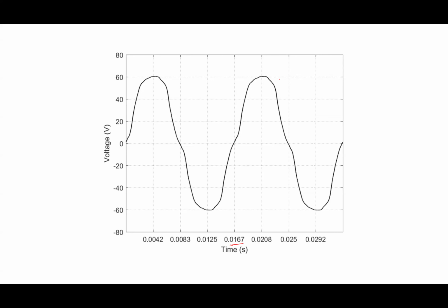This waveform has within it a bunch of harmonics. And if I looked at this carefully, what I would find is it's got a lot of 60 hertz. It actually has a fair amount of third harmonic, which is 180 hertz, a bunch of fifth, a bunch of seventh, which would be 420. Right? It has a bunch of those frequencies. It doesn't really have any of the even ones. So 120 hertz would be 2 times 60. It doesn't have much 4 times 60, doesn't have much 6 times 60, but it has a lot of the 300 and a lot of the 420.